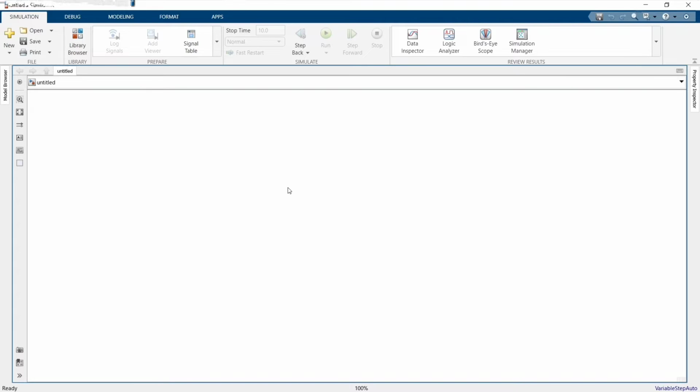I also need one signal port, for switching off and switching on my IGBT. So for that I will use an in port. There are various kinds of ports used for modeling: the physical connection ports and the in ports. In here I will provide my name S plus signal port.